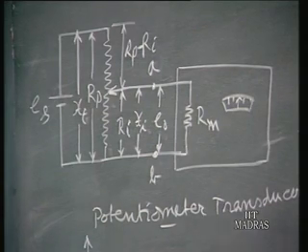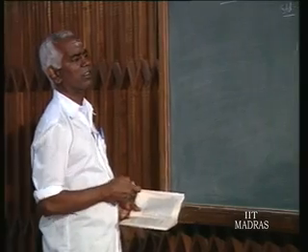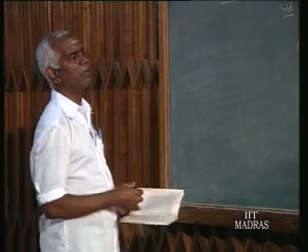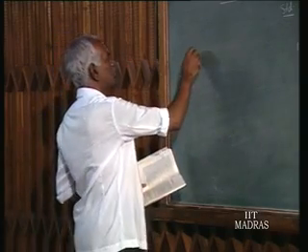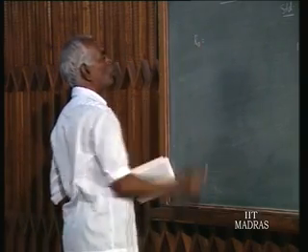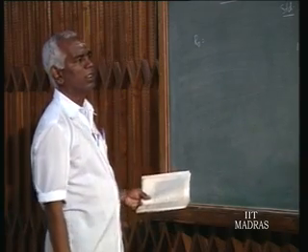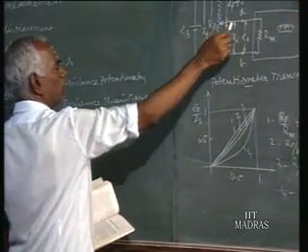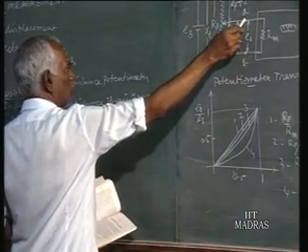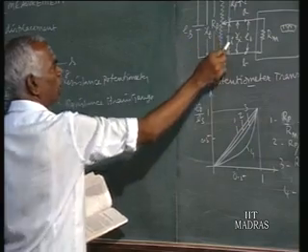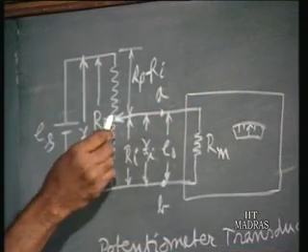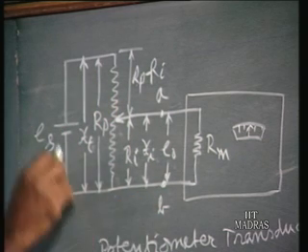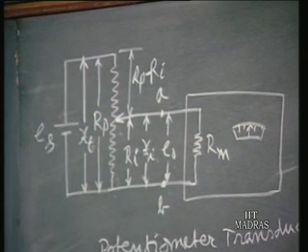So before connecting the voltmeter, whatever be the resistance seen from the points A and B in the circuit, we will call it Ro, the output resistance of the potentiometer circuit. We have to go from A to B, that is why we have to find the equivalent circuit. From A to B, one resistance Ri corresponding to Xi, and the other parallel path is Rp minus Ri, and again you come to point B, and Es is short circuited for the purpose of equivalent resistance.